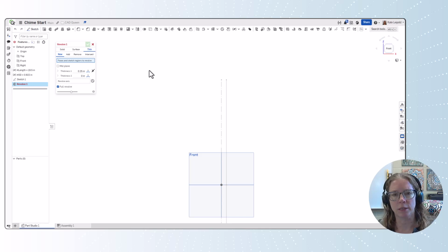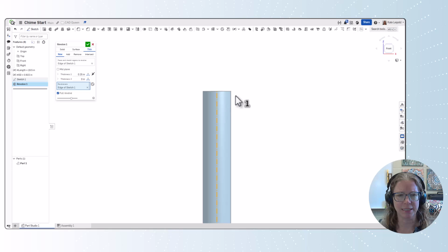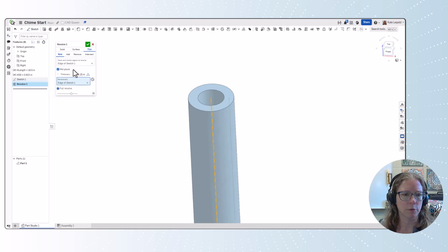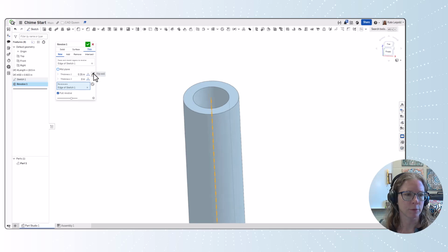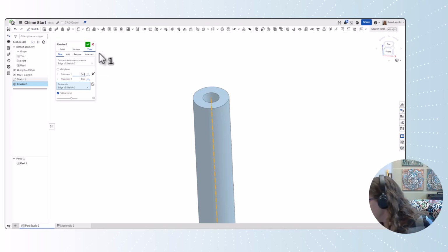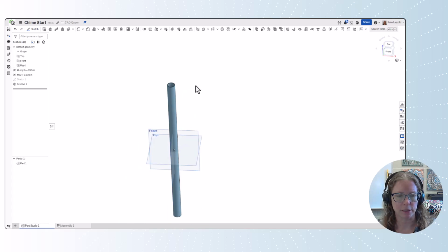This is going to be a thin wall revolve. So essentially, this is my sketch, and my revolve axis is here. So it's spinning that line around, but it's adding a wall thickness. We've got three different ways to add wall thickness. We can add it inside, we can add it outside, or we can add it to the midplane. We're going to add it to the inside, and we're told that nominal wall thickness for 3/4 EMT is 0.049. Again, I could build this as a variable if I needed. Okay, and there is the start of my tube.